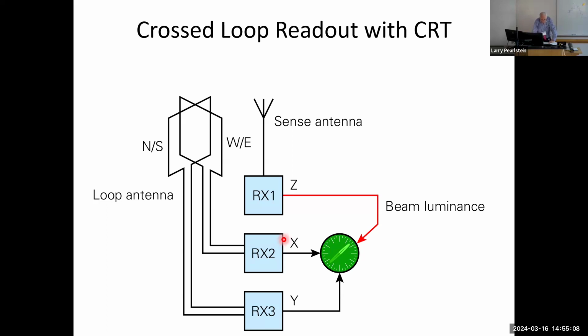The next electronic invention is the radiosonde, and it also matured in the 30s. A compact radio transmitter is attached to a balloon. It transmits atmospheric pressure, which, as the balloon goes up, in fact gives you altitude, temperature, and humidity. Humidity is determined here by a salt deposit on a glass plate, and the more humidity, the more conductive it becomes, and it gives you your indication of relative humidity. Today, we can include additional measurements such as chemical pollution and location.